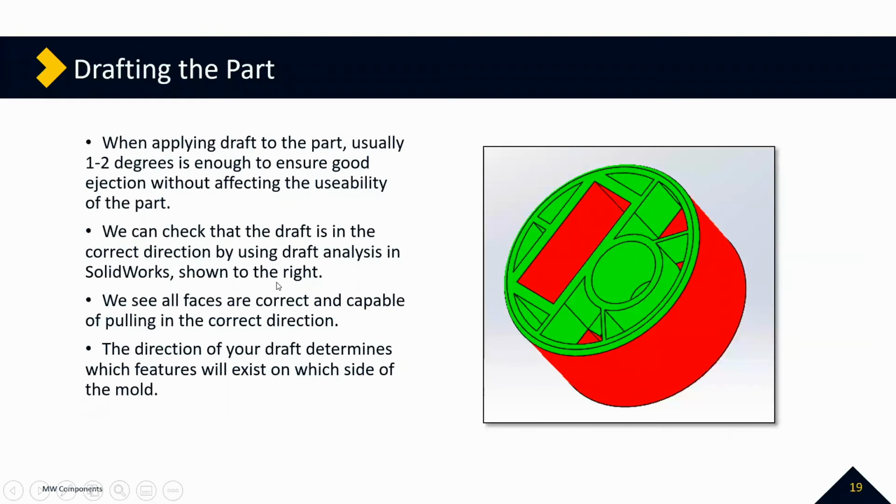Awesome. What do you do in the design phase to combat shrinkage of plastics? Right. So again, I'm going to go back to the technical data sheet. Once we're really serious with the customer, we start designing the product for the mold. We're going to start looking at the specific resin we want to use. At this point, the resin's usually been spec'd out, and we've landed on one specific grade of resin.